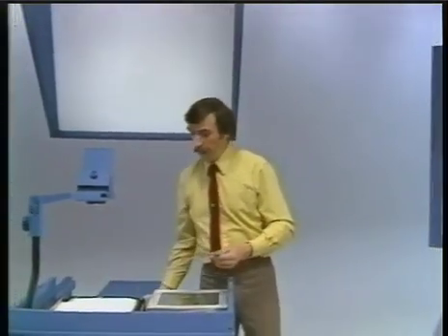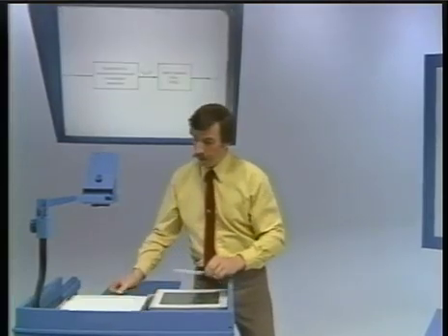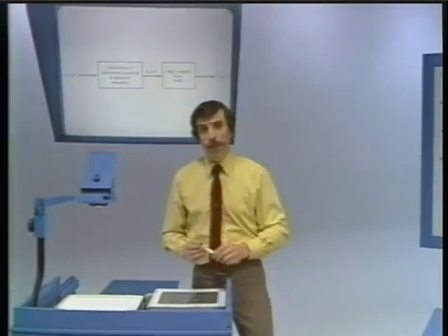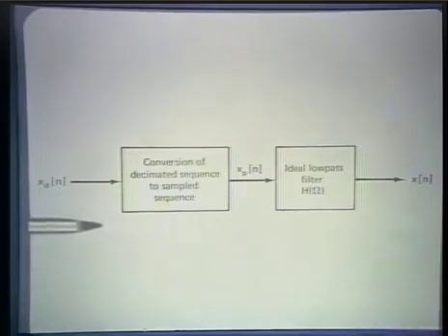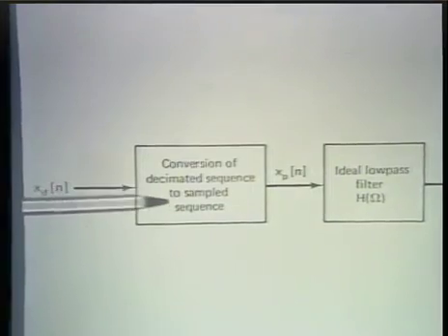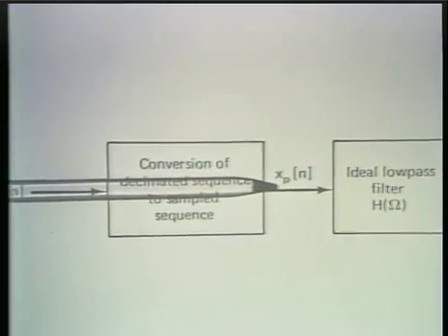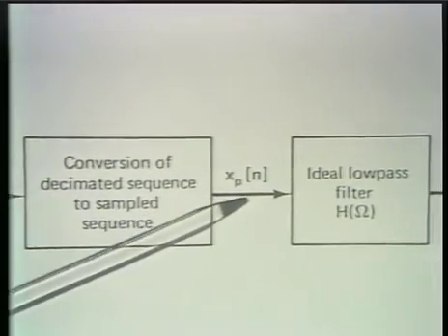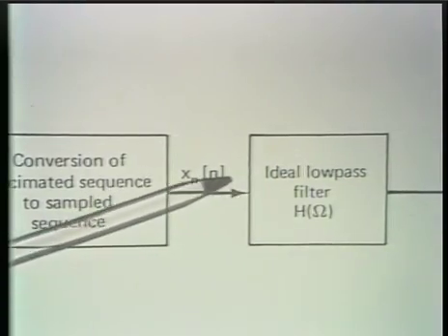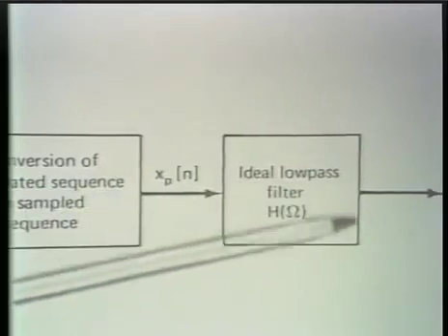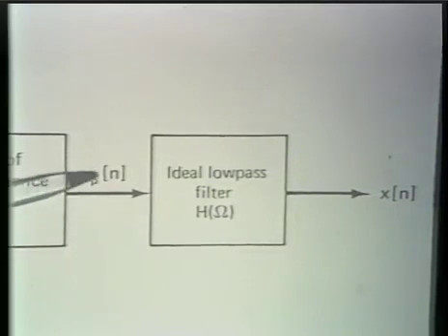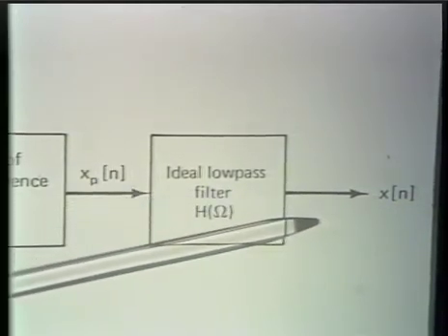So in the opposite operation, what we would do is undo the decimation step, and that would consist of converting the decimated sequence back to an impulse train and then processing that impulse train by an ideal low-pass filter to do the interpolation or reconstruction, filling in the values which in this impulse train are equal to 0.